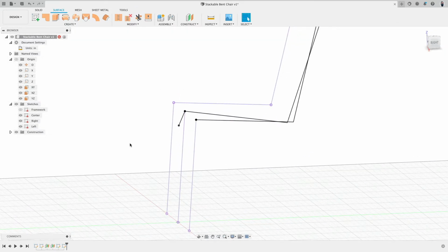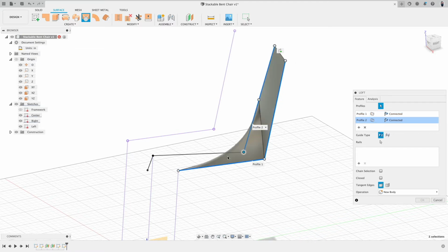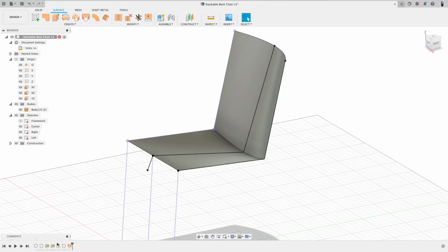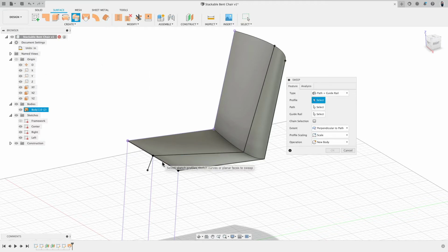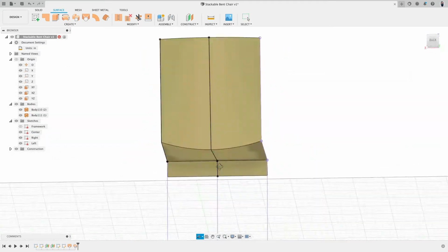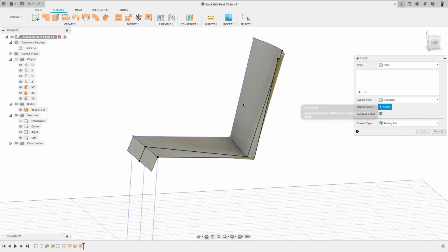Okay, good. So this now we have. That looks pretty nice. So loft all this. There we are. And you noticed I didn't project here the lines in for the sketch. I could do this if I want to. Or could simply now go, we never looked into the sweep command. In SketchUp, this is called follow me. I can now select this line and say follow or move this line along this path. Very good. So you see there, we actually created a nice extension of that. Then these two surfaces we will stitch together, and then we can go back and take a look at the filleting.